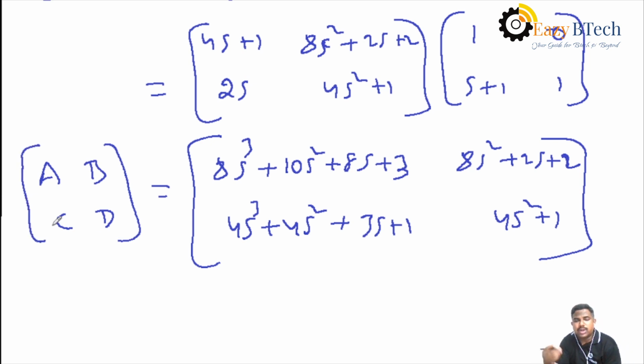Okay, in this way, you have to find out any two-port network parameters, either cascade, series, or parallel connection. Suppose here in this problem, we found ABCD parameters, but we require H parameters. Then we know the relationship between the two-port network parameters. By using that relationship, we can find out the H parameters in terms of ABCD parameters.